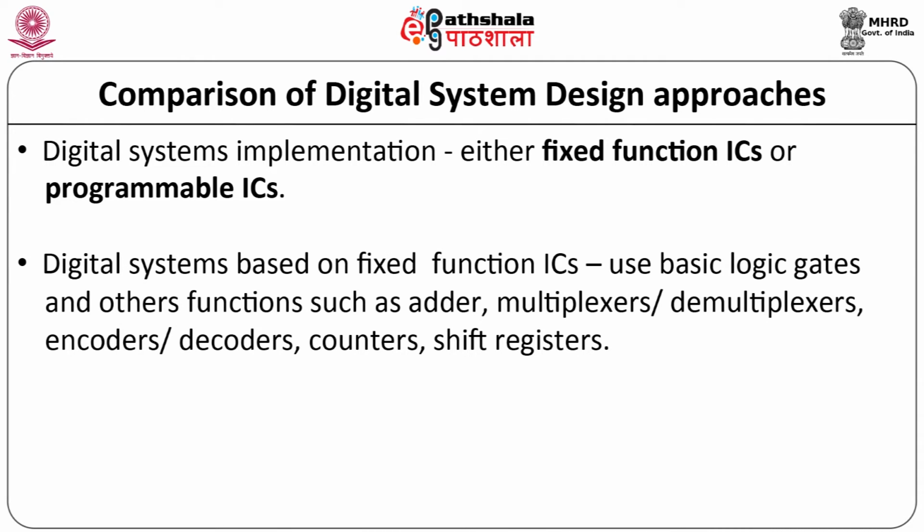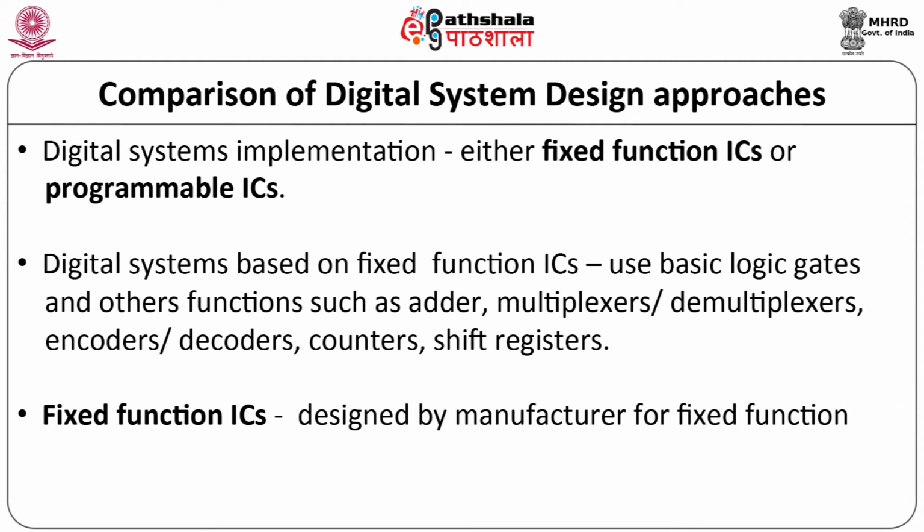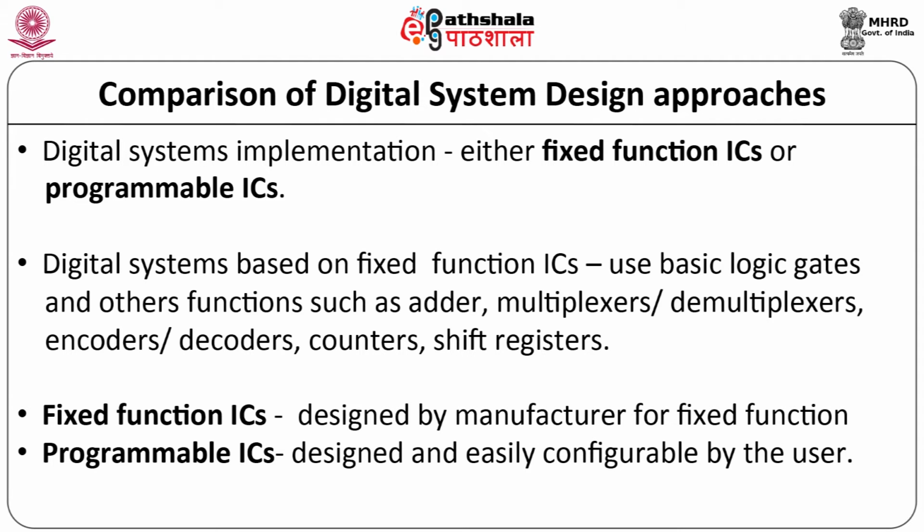Digital systems based on fixed function ICs normally use basic logic gates and other complex functions such as adders, multiplexers, demultiplexers, encoders, decoders, comparators, counters, shift registers, etc. Fixed function ICs are usually designed by the manufacturer for providing fixed functions, whereas programmable ICs are designed by the manufacturer in such a way that the user can easily configure and reutilize them.